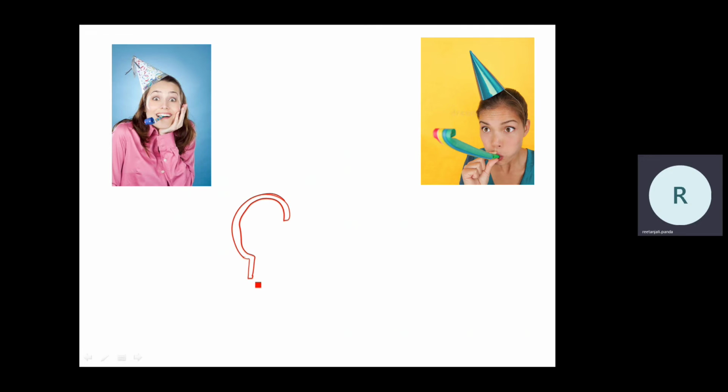When pressure acts on the fluid of the Bourdon tube pressure gauge, that fluid makes this Bourdon tube straight. So initially it will be C shape. After applying pressure, this is the deflection we are getting. Okay, because of this deflection, what happened? There will be one pointer and one link attached to the pointer. So when it moves, it also makes this pointer move.